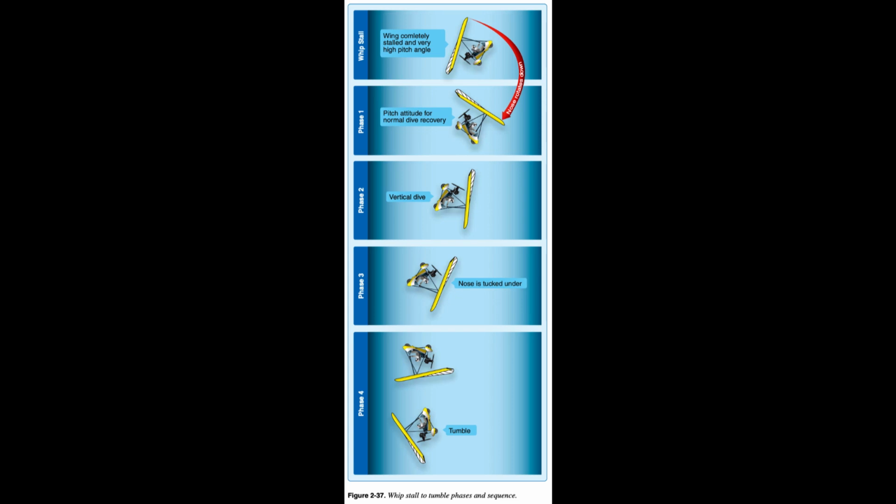In a WSC wing, most of the area of the wing is behind the CG, about 3/4. With the tips and aft part of the wing having the greatest drag, and the weight being forward, an immediate and strong nose-down moment is created and the WSC nose starts to drop. Since both the relative wind and the wing are rapidly changing direction, there is no opportunity to re-establish laminar airflow across the wing.